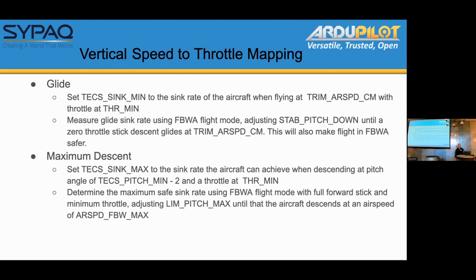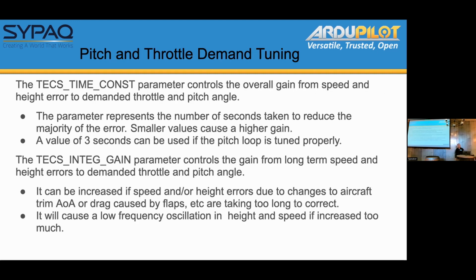Okay, so we've done the maximum descent. Then we get into the tuning. Now, before I talk about tuning, I just thought I'd run a little test and show you how you can use guided mode as a good way to set up climbs and descents for TECS. The reason I like guided mode is because when you click on the map and say fly to, and you give it an altitude, it'll circle that point. So you don't have to worry about the aircraft positionally.